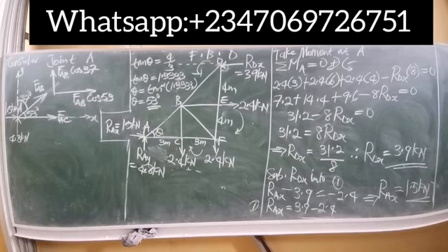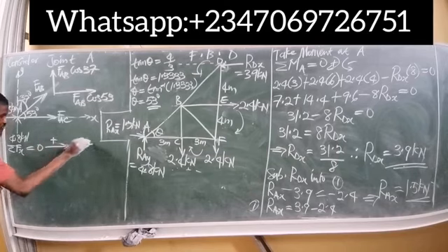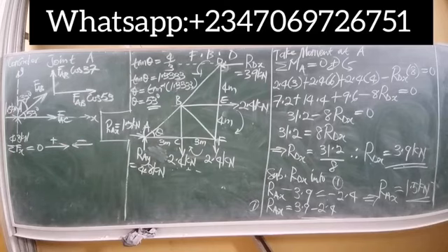So having done this, it's simple from here. The next thing to do is to employ your equilibrium law. From the equilibrium law, the summation of Fx, the summation of horizontal forces, is equal to 0. Not forgetting, forces that point to the right are positive, forces that point to the left are negative. So sum all the horizontal forces here and equate to 0. Now we have 1.5 kilonewtons pointing to the right, so this force is positive. Pick it out, 1.5.